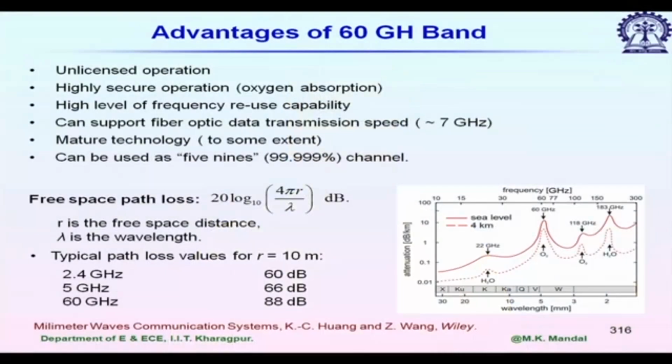So, next we are going to discuss the 60 gigahertz channel in detail in the presence of noise. From the previous slide, we have seen that because of the higher frequency we have very high attenuation due to path loss, and it is 28 dB higher compared to 2.4 gigahertz. If I compare this with the attenuation due to atmosphere, that is only 10 to 12 dB per kilometer. So, the path loss is much higher compared to that value.